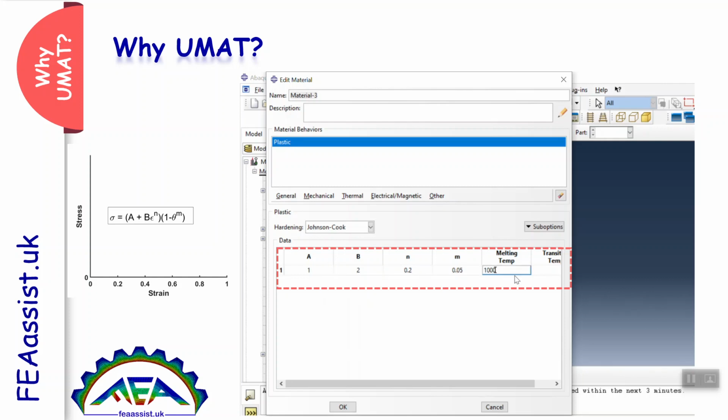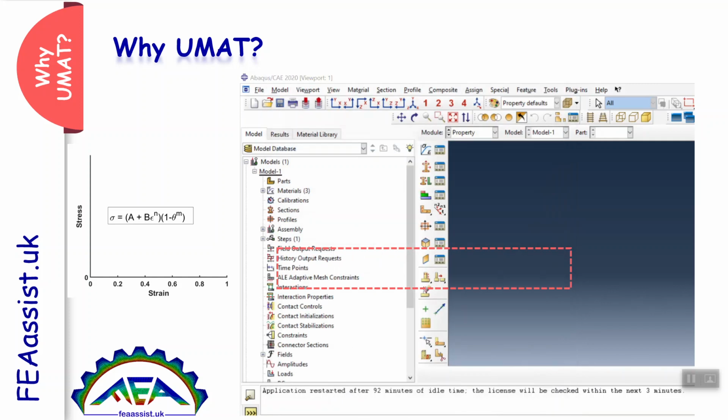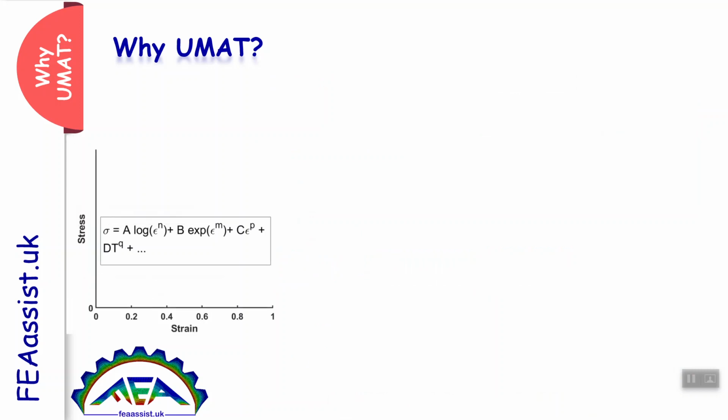Here it is the Johnson-Cook model. It is a more precise solution because you have an equation for all your points. But consider you have a material or a new constitutive equation. The equation between stress and the components is very new, which is not included in Abaqus, and you don't have points.